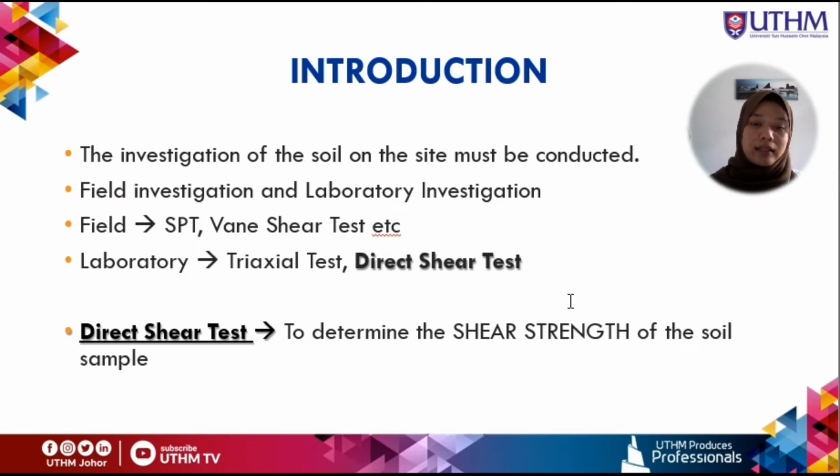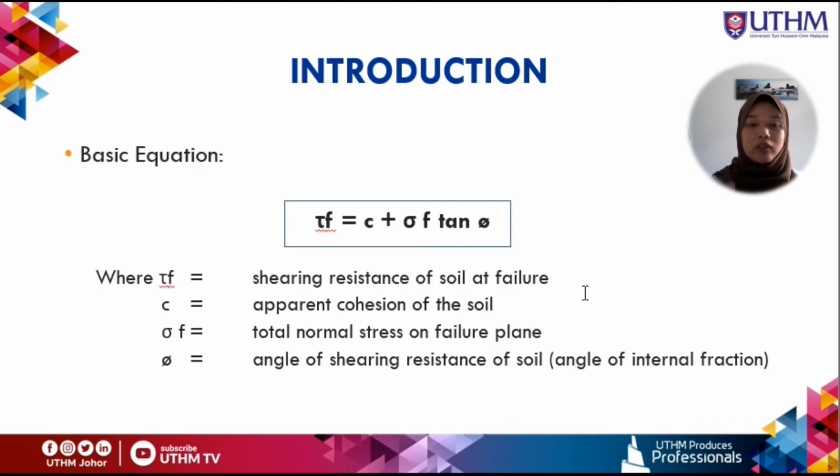The direct shear test is conducted to determine the shear strength of the soil by using the shear box inside the laboratory. When we conduct the test inside the laboratory and the results are obtained, we can compute the values inside this equation to get the shear strength of the soil. This is the conventional method, where we conduct the test inside the laboratory. In this project, we conducted a direct shear test by using numerical modeling in PLAXIS.